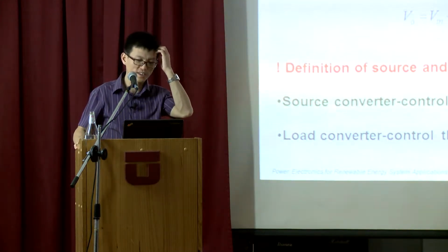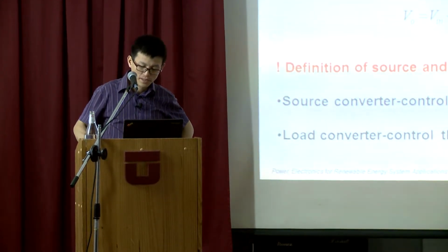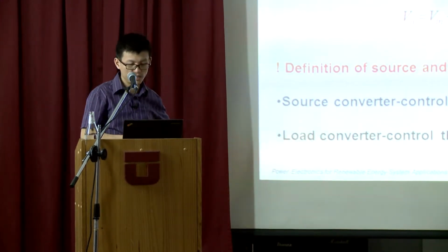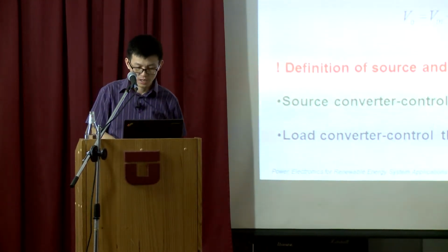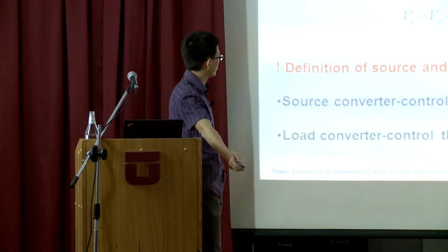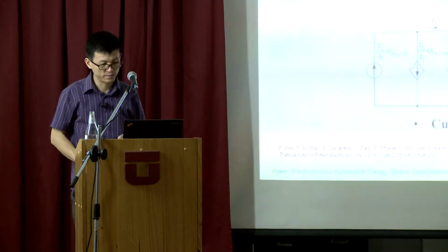I think the first year students can do this if you give them the concepts. Okay. So the source converter controls the bus voltage, and the load converter controls the load current. Okay, control the current and power. It's the key thing you should be aware of.